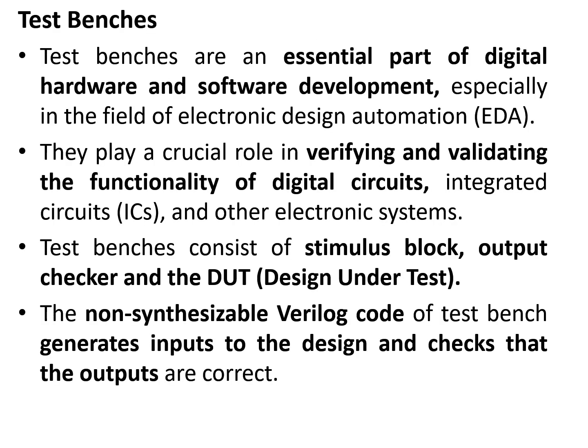Test benches. Test benches are an essential part of digital hardware and software development, especially in the field of electronic design automation. They play a very crucial role in verifying and validating the functionality of digital circuits, integrated circuits, as well as other electronic systems. These test benches consist of a stimulus block, an output checker, as well as the design under test, DUT. The non-synthesizable Verilog code of a test bench generates inputs to the design and checks that the outputs obtained are correct.